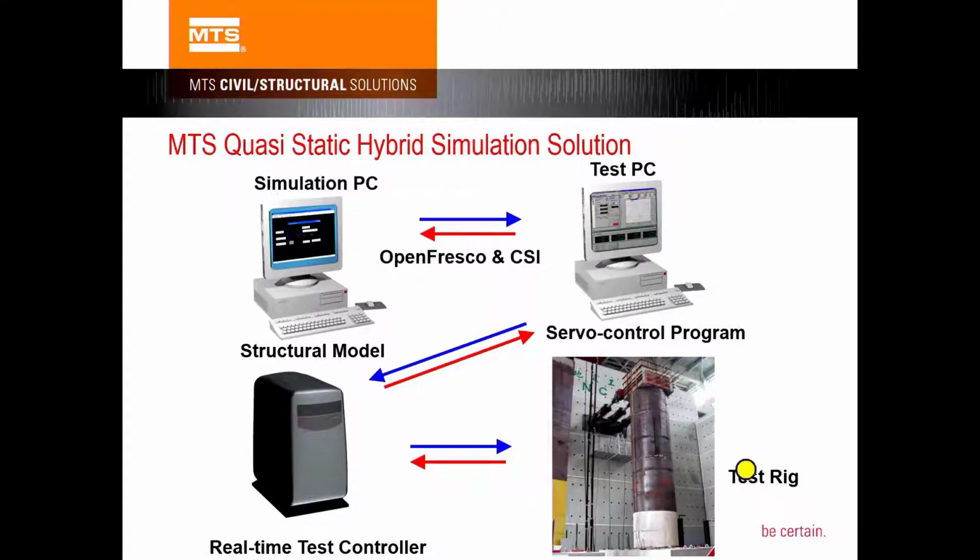So our solution is, you have a FE computer, a simulation PC here, and the simulation generates a command, and the command is sent to OpenFresco. That's the software developed by UC Berkeley, and then OpenFresco sends it to another software developed by MTS called the Computer Simulation Interface.